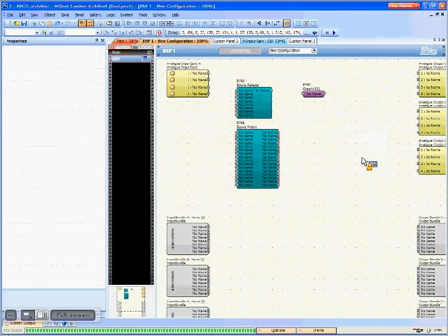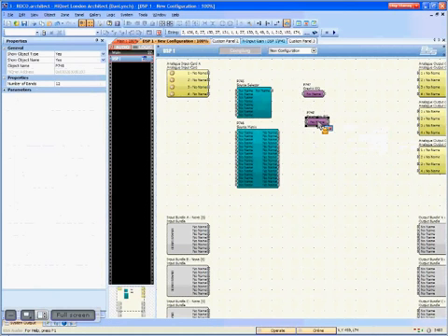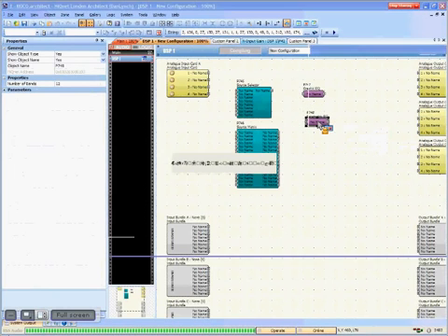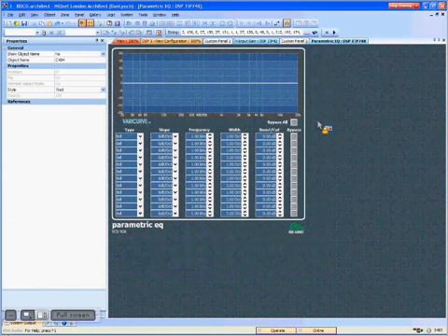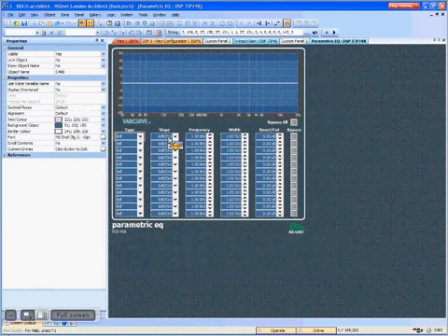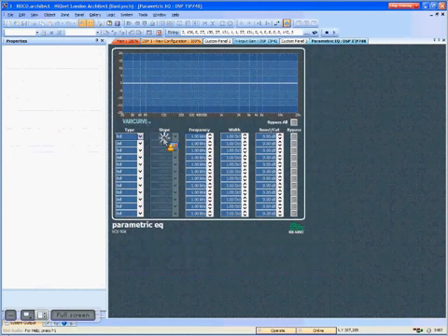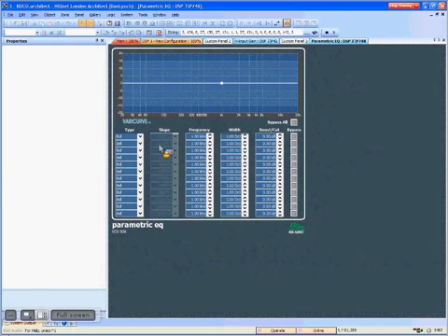On the parametric EQ, you guys have dealt with speaker manufacturers' tunings. What's the most annoying thing in the world? You look on the sheet from the speaker manufacturer and it tells you the type of filter. Gives you either the slope or the width. But the problem is, on a lot of manufacturers' sheets, it doesn't tell you the width. It tells you the Q. Instead of width, it says Q.